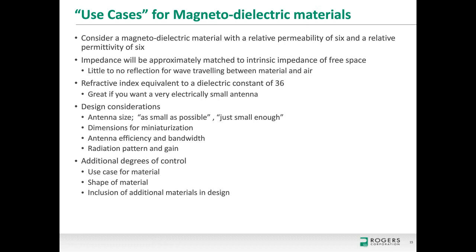Going to another structure, like a PIFA antenna, may allow you to make it even smaller. When you're going to an effective size that's something like lambda by 50, you're going to be making a lot of trade-offs in the antenna's performance. So if you're okay with a narrow bandwidth, narrower than you would see in this larger patch example, and maybe a lower efficiency, it may be possible. We haven't evaluated anything that's that electrically small.